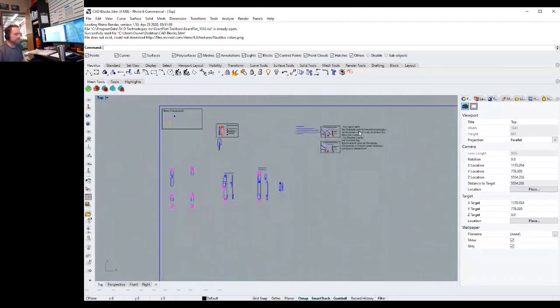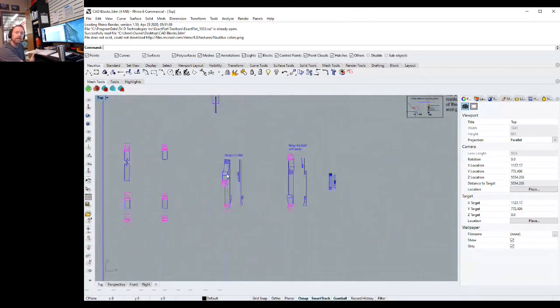So the standard is a 1-inch side release buckle, with a 1-inch box stitch, with or without a hook. So you develop your standards, and then you can apply this to, say, a center console with wings that go out and connect those wing panels to the gunnel. Those buckles should be the same every time. Why should they be different? So those buckles should be the same.